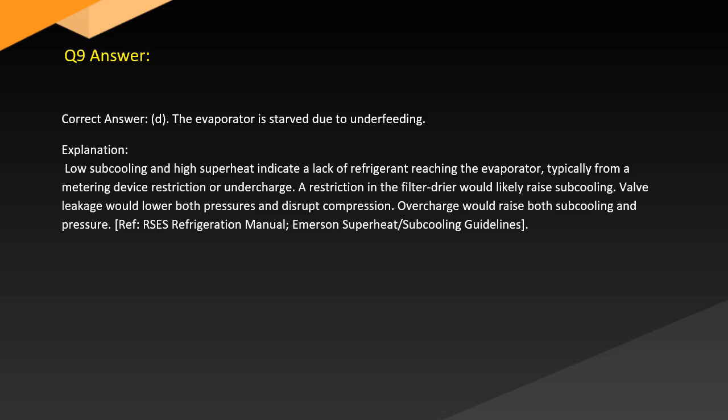Valve leakage would lower both pressures and disrupt compression. Overcharge would raise both subcooling and pressure. Ref. HVACR Refrigeration Manual. Emerson Superheat Subcooling Guidelines.